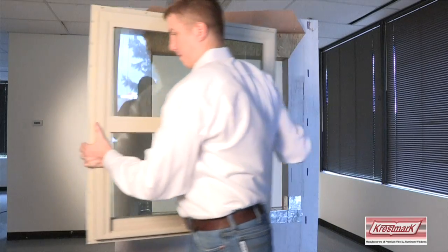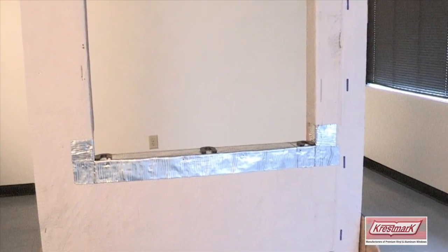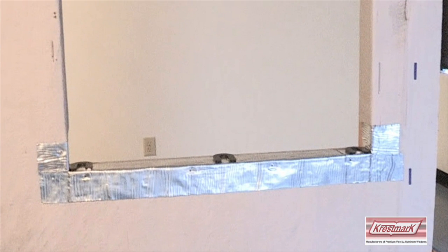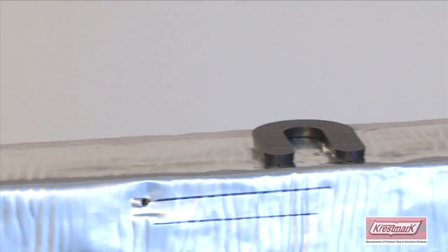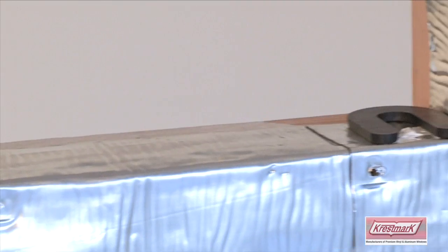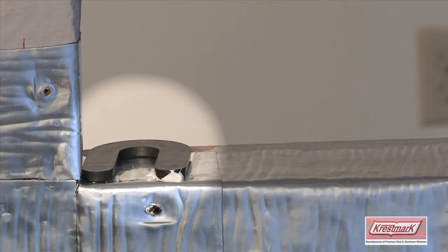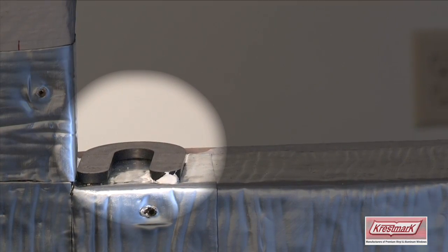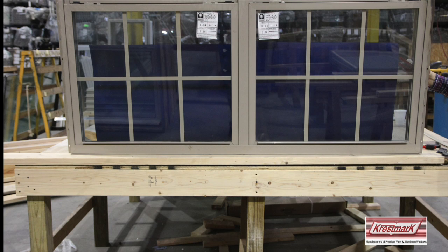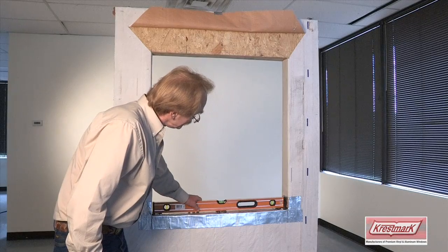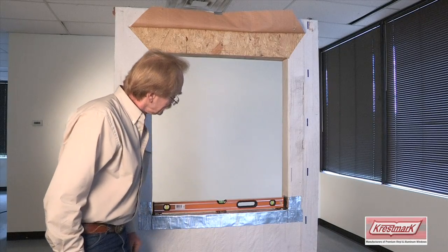Remove the window. The sill of the window must be supported in a straight and level position at a minimum of 3 points, at either end and in the middle. Place 1/4 inch shims on the sill of the rough opening, one in both corners, and, for this demonstration, a single shim to support the middle of the window. A small dab of sealant can be used to help keep the shim in place. Shims are recommended at a maximum of 12 inches in windows wider than 30 inches. For twin, triple, or quad units, shims must be placed under each mullion. Again, check that the shimmed surface is level and ready to accept the window.